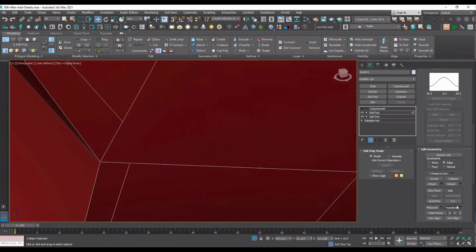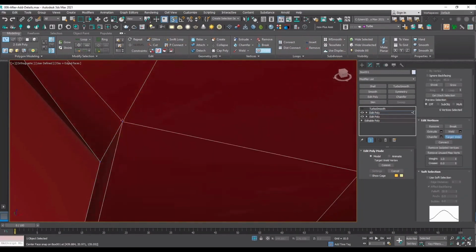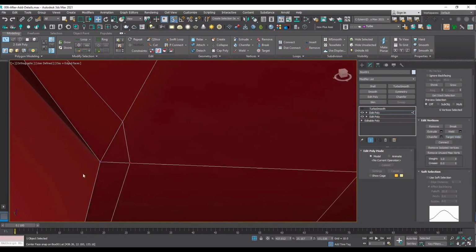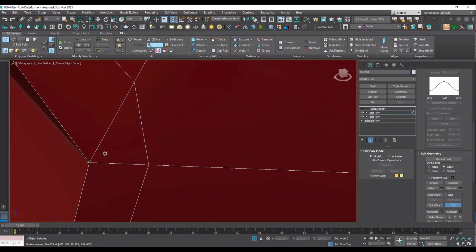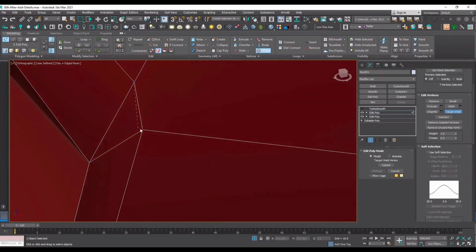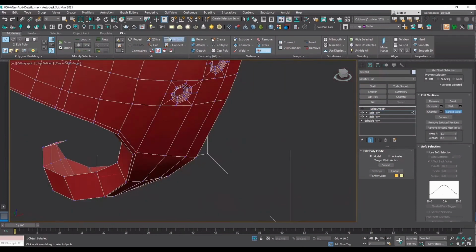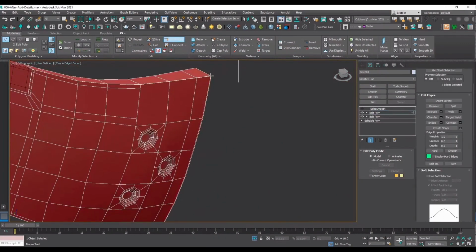And also I can manually cut this vertex to that and just pick up my target weld tool and connect these vertices to each other. Or I can just manually pick up again my cut tool and set up the median point, and then pick up the target weld tool and connect both to that point in the middle, and then just keep adding vertices like here.